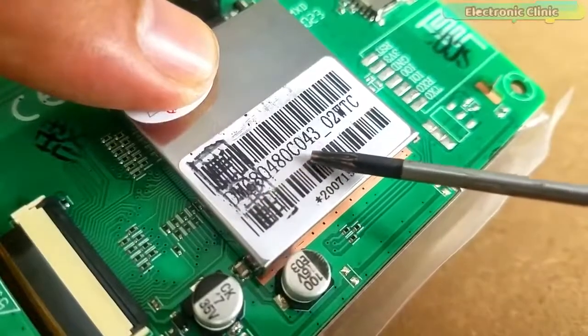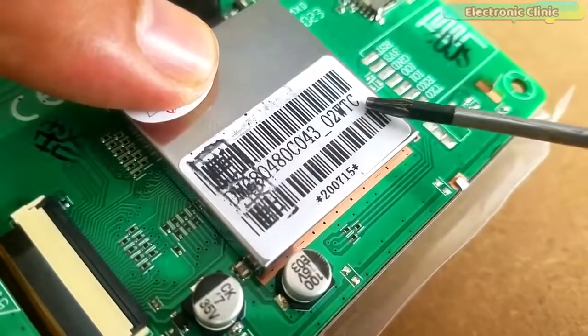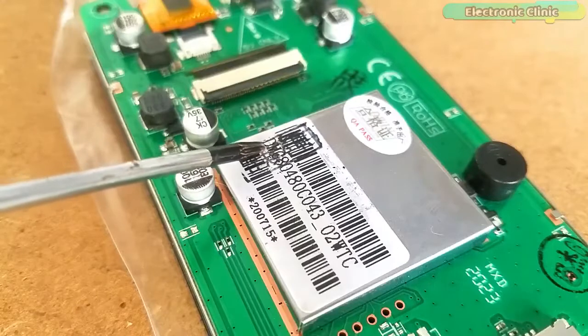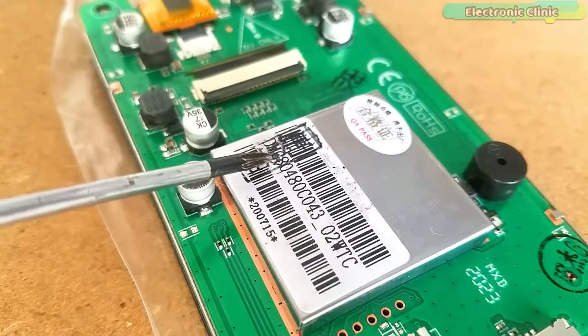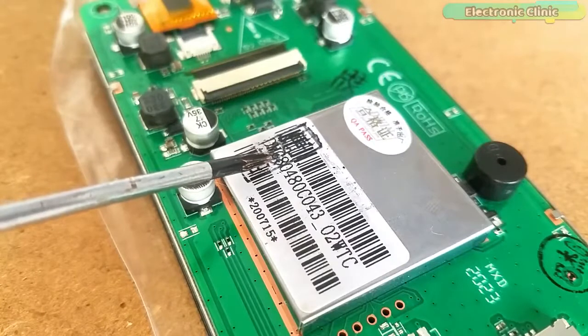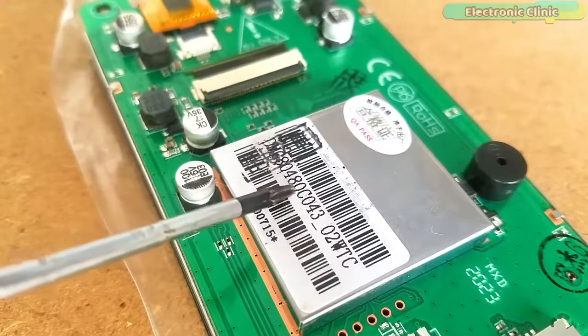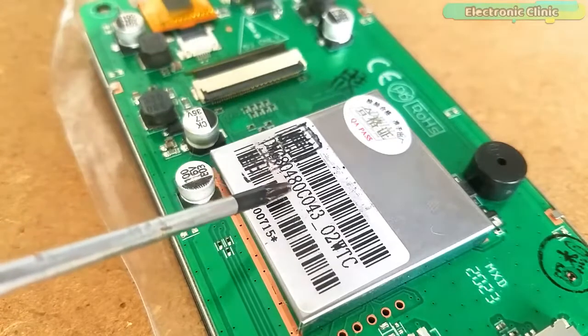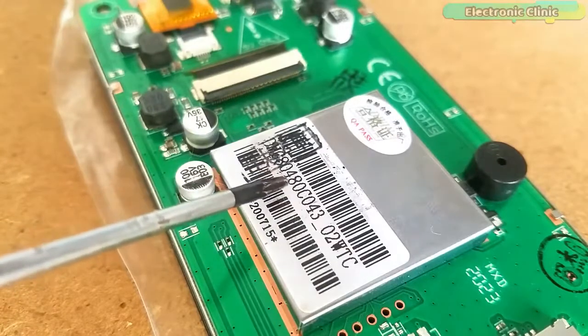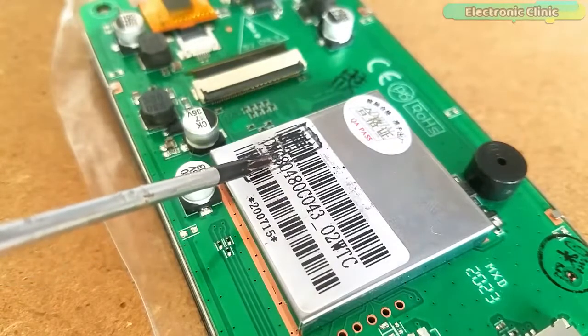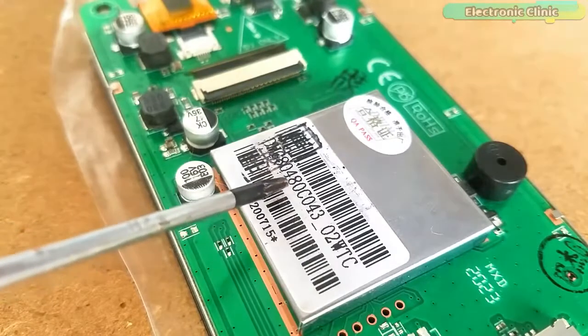The DWIN Smart LCMs follow a naming rule. The first 2 characters, DM, represent the product line code. The third character represents the color code. For this touchscreen, G means 16.7 color. The next 5 digits represent the touchscreen resolution. For this touchscreen, 80480 means this is 800 by 480.